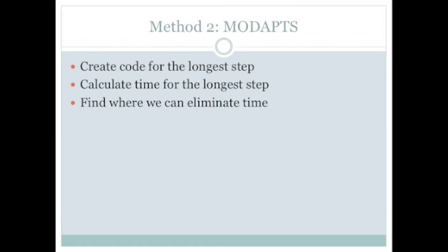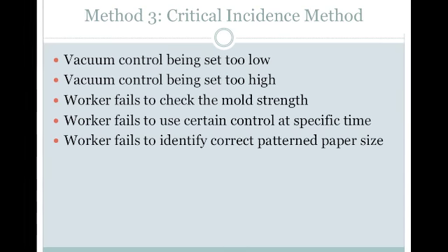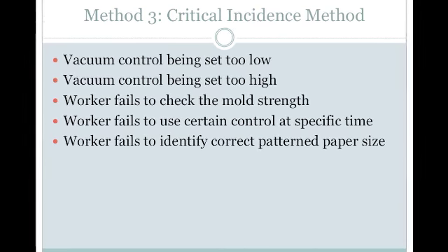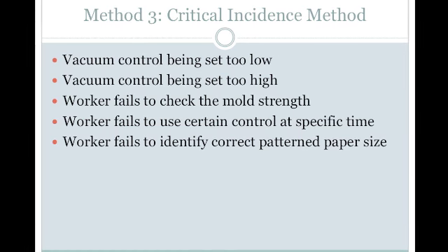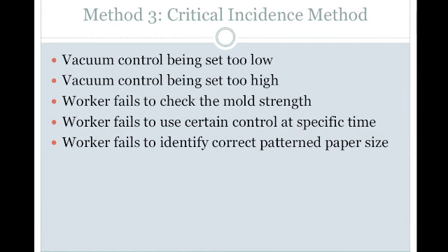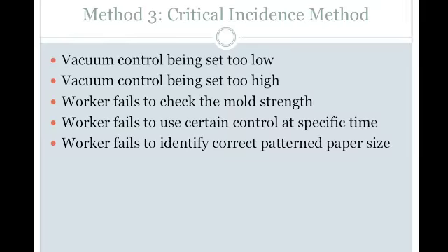After performing our time study and establishing the longest part of our process, our team used MODAPTS to break this part down. By combining our MODAPTS analysis with our potential layout changes in SketchUp, we will be able to give concrete reasoning on the potential time that could be saved. Next, we conducted a critical incidents analysis. We interviewed 3 different individuals and asked about their memories of actions or direct observations of others. We found 5 main problems shown here.